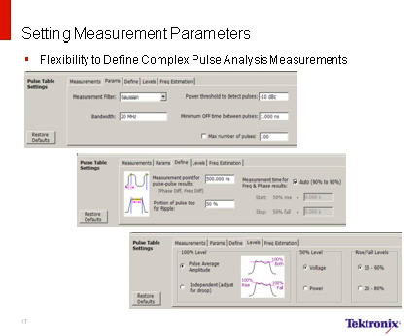When considering the setting of pulse measurement parameters, the user interface for the automatic pulse measurement tool provides the flexibility to analyze a variety of complex radar pulses. In addition to filter, bandwidth, threshold, and timing information, other parameters such as defining where the measurements are to be made or how they are to be calculated enhance the usability of automatic measurements in order to replace older tools.